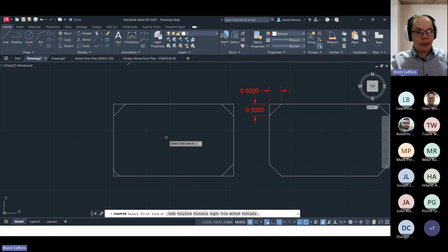No fun tricks with this one, really. If you set your chamfer distances both to 0, it'll make your right angles again. But there's no fancy way of taking two parallel lines and making a connection between them. Chamfer doesn't do that, only fillet does.